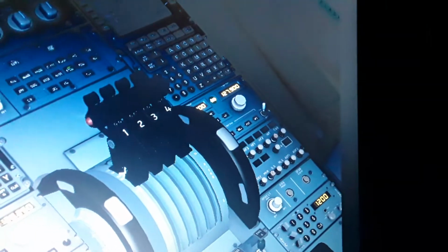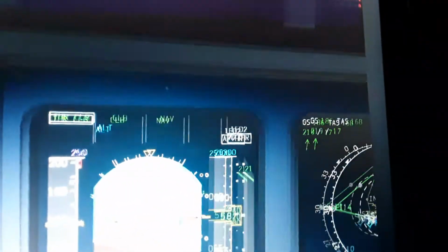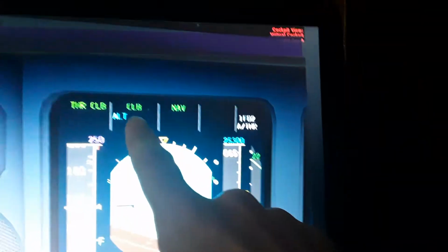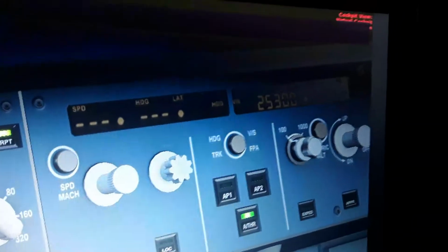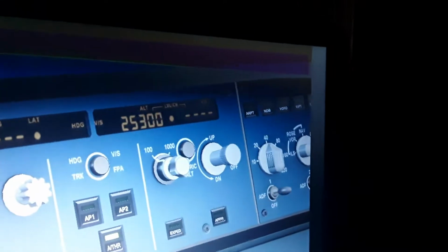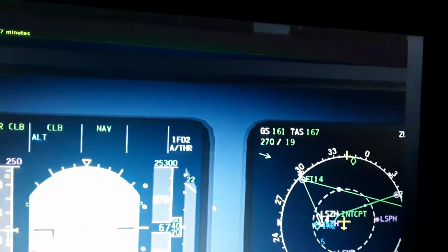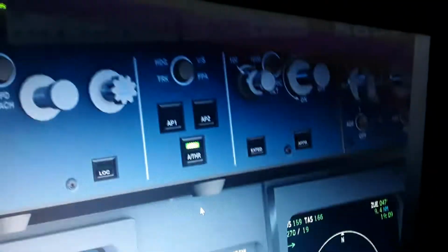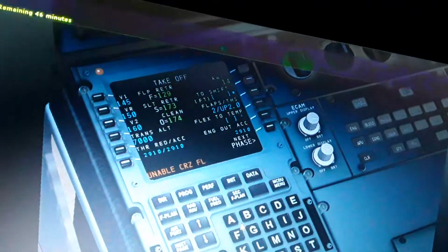So now it's the max takeoff, MCT and glide. You can see the thrust glide right now displayed here for the auto thrust system. These are the autopilot modes, the glide and the nav, and the altitude hold, which I have right now. Altitude selected 35,300. When I press in these buttons, the modes are managed. When I pull them out, the modes are selected by the pilot. When I press them in, they are managed from the flight management computer here and the autopilot.